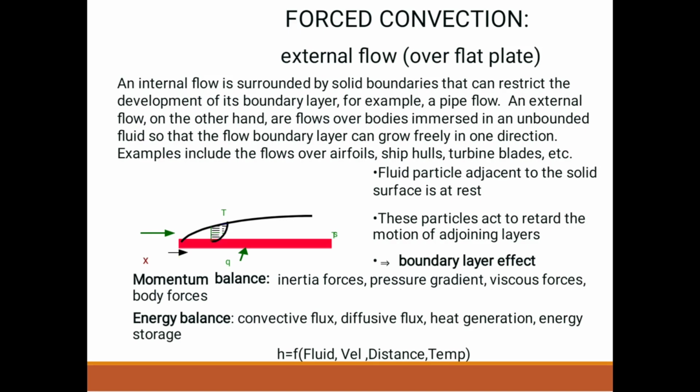The fluid particle adjacent to the solid surface is at rest. These particles act to retard the motion of adjacent layers. In the momentum balance, the inertia forces, pressure gradient, viscous forces, and body forces act on it. The energy balances are convective flux, diffusive flux, heat generation, energy storage, etc.